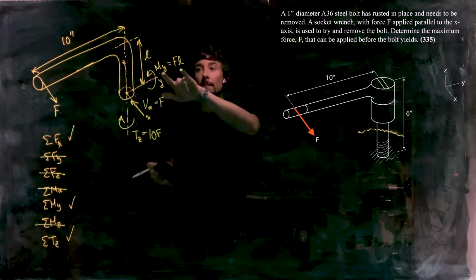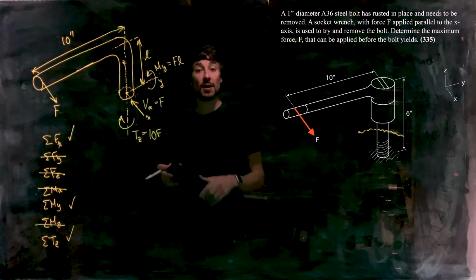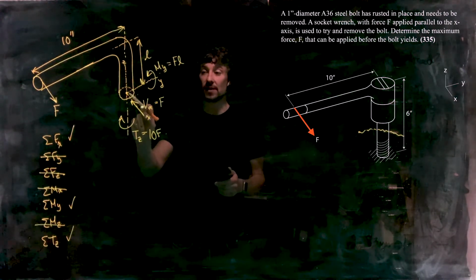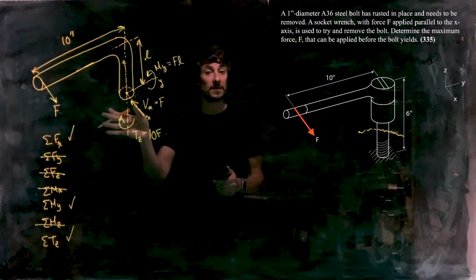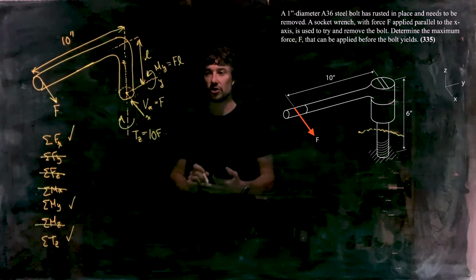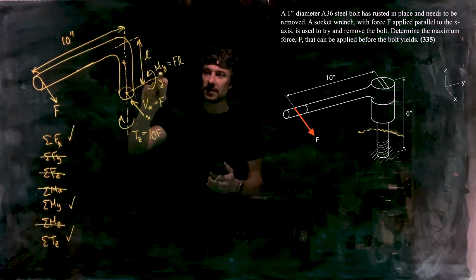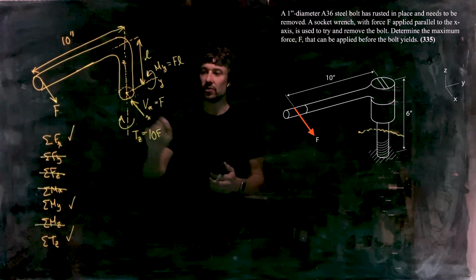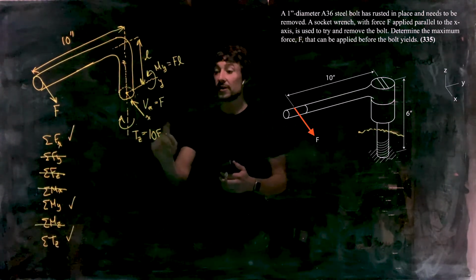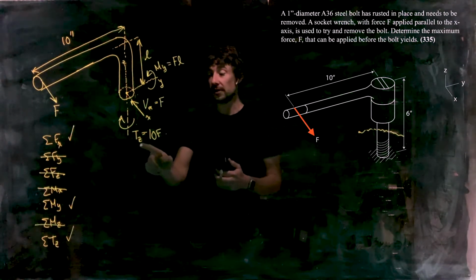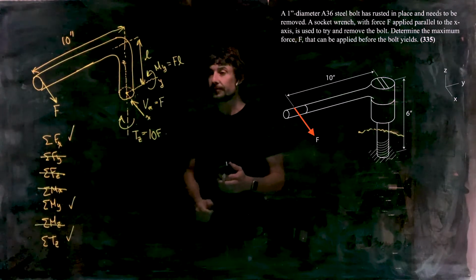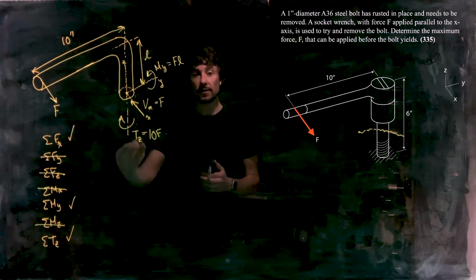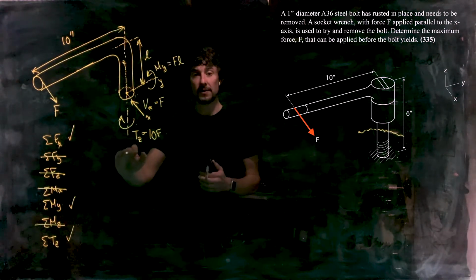We know that bending stresses due to internal moments are generally large compared to shear stresses caused by internal shear forces, with the exception of pins, which have very small moment and larger shear. Here, the moment is going to give rise to a normal stress that's significantly larger than the shear stress due to the internal shear force. Shear stresses due to torques, though, are generally significant.